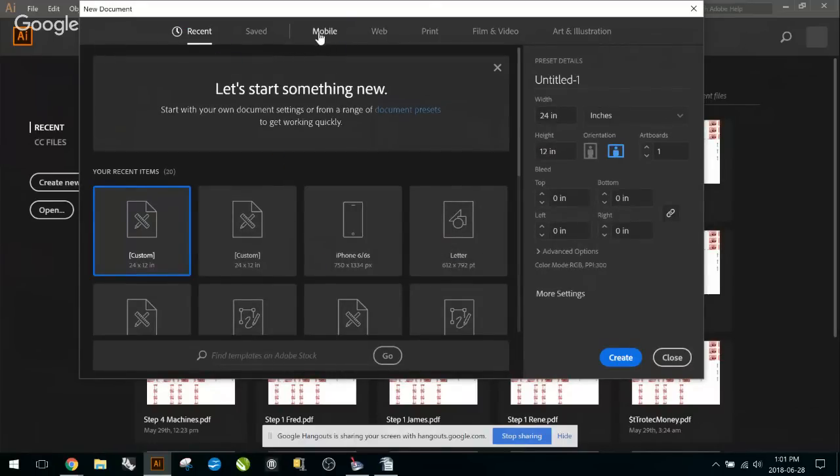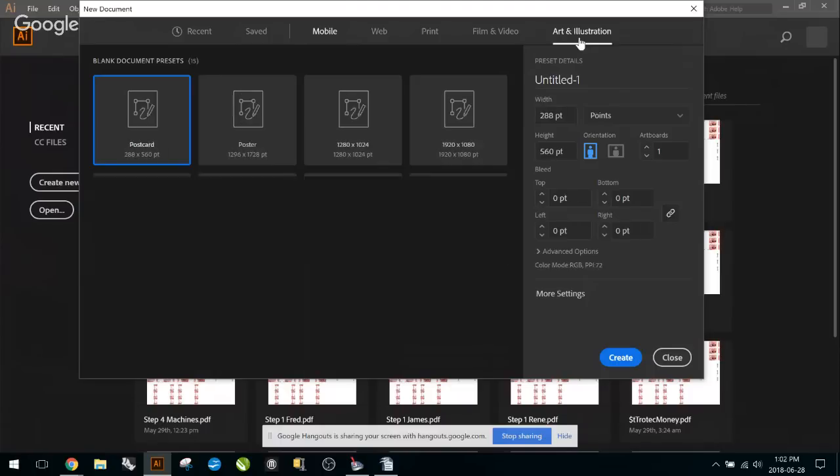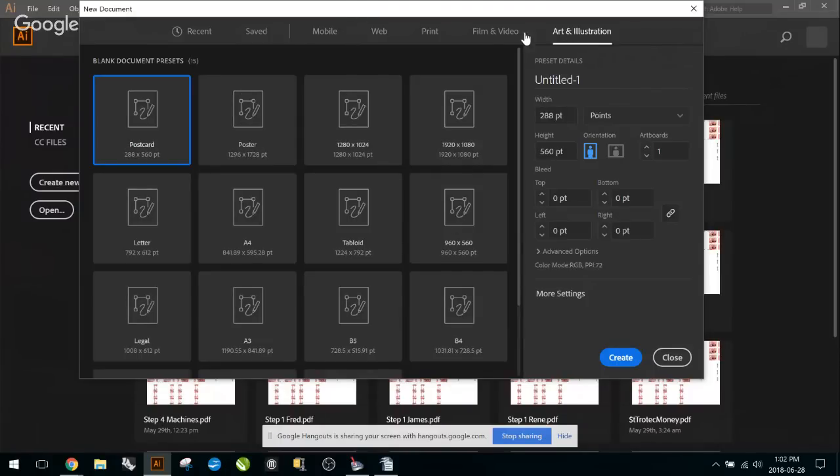And you can use the document presets that we have here. If you're going to choose any of these, I would suggest not choosing the print. Pretty much anything else will be fine for this, and the reason why is because they use an RGB palette for your coloring. The laser needs to read RGB colors in order to be able to register your lines. So just go in here and click on any of these preset documents, and we're going to change the parameters of it anyways.